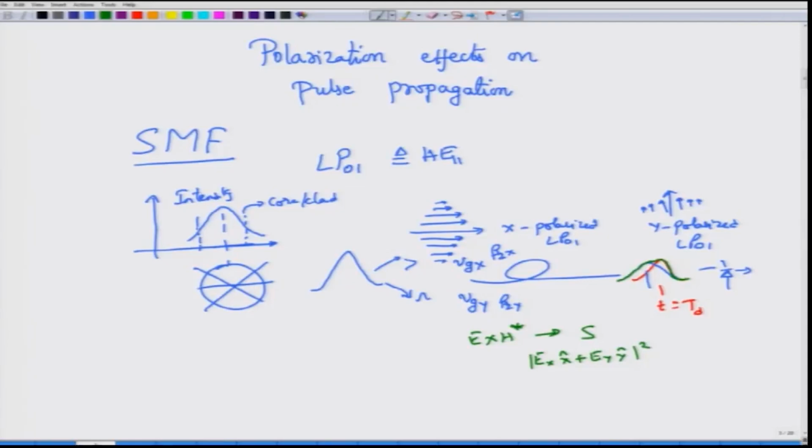So, this kind of a dispersion which distorts the pulse simply because even though you considered single mode fiber, the fact is that single mode fiber supports two fundamental modes, and if the fiber is made out of a material, or if the fiber exhibits any property which allows you to have different values of Vgx and Vgy, and this phenomenon wherein the x and y polarized modes actually travel with different velocities is called birefringence, okay. And all optical fibers have some amount of birefringence.